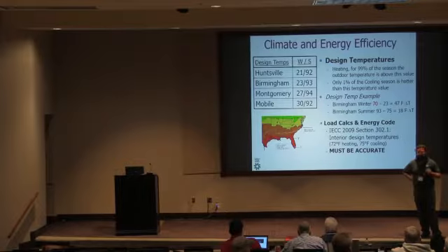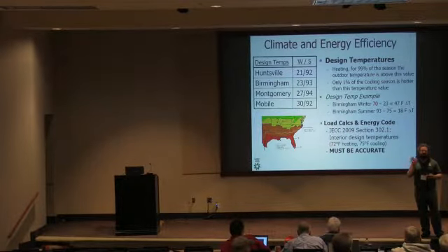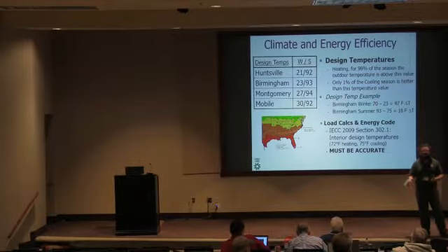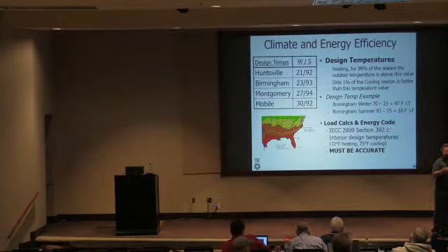But definitely, you could see a tighter spray foam house that then has an elevated level of radon because it's a tighter home. That said, lots of times we're reducing uncontrolled air changes and we're putting back in mechanical ventilation. If I do a spray foam roof line job correctly, I'm going to baseline with a blower door test before I do it.